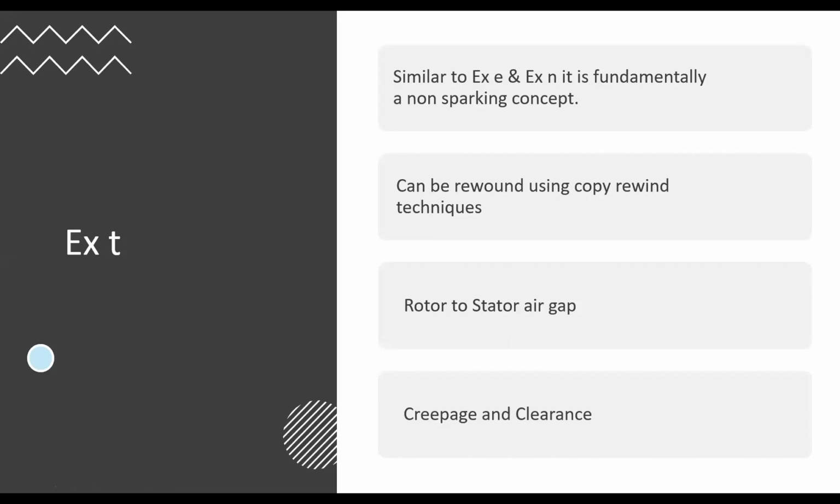They can be quite dangerous, dust explosions, because one explosion then leads to another, classed as dispersion. If you drop something in a dusty environment, you see a cloud of dust coming up. Yes? So a little explosion will cause dust to rise into the air. That is then ignited, that will explode, and then another area of dust will rise and will also get ignited.